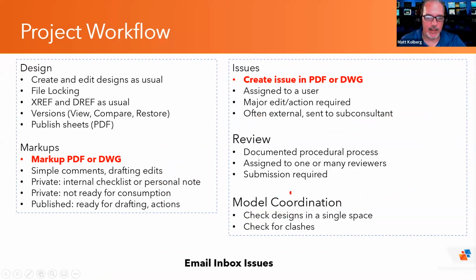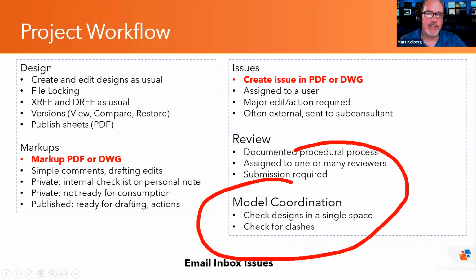Model coordination, finally, is where you can take your designs and all of the other sub-consultant models, put them in a single three-dimensional space, and compare them against one another. You're looking for clashes, maybe you're checking if your first floor lines up with your parking lot elevation, for example.